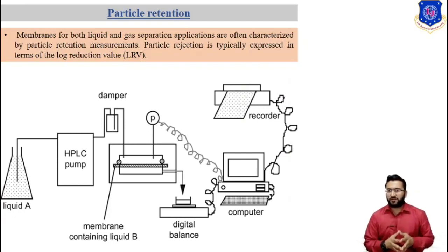Such a situation will also lead to the large pores becoming partially or fully blocked by the captured particles. Thus, the pore size distribution will apparently change with the extension of filtration, which results in overall surface cake buildup, filter surface fouling, particle aggregation and particle bleed, which can change filter retention and permeability.